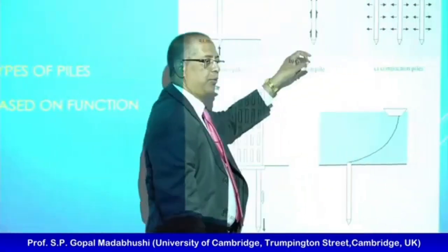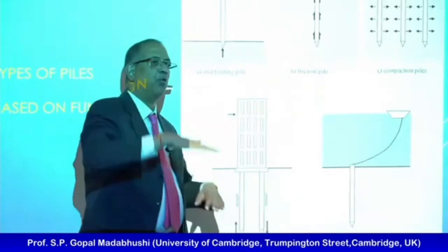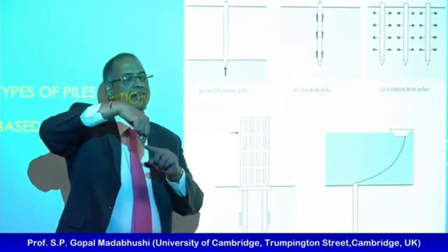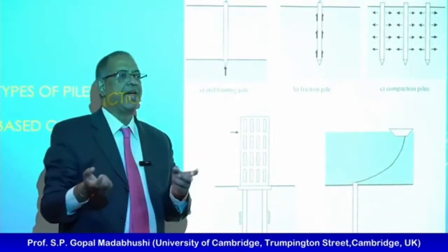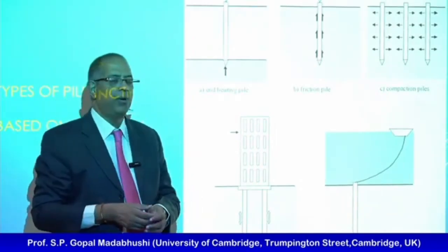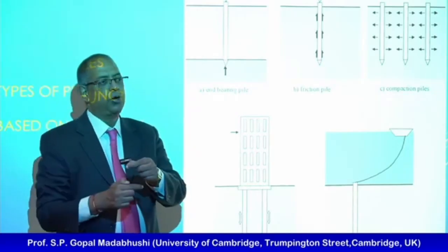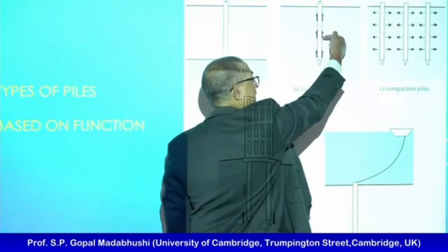I don't know if you thought about this or not. If I want the frictional resistance here, at any elevation I take the vertical stress which is acting down and multiply it with a factor Ks to turn it into a horizontal stress. Ks is some form of earth pressure coefficient, to convert the vertical effective stress into horizontal effective stress. That's fine. That gives me this bit, right?